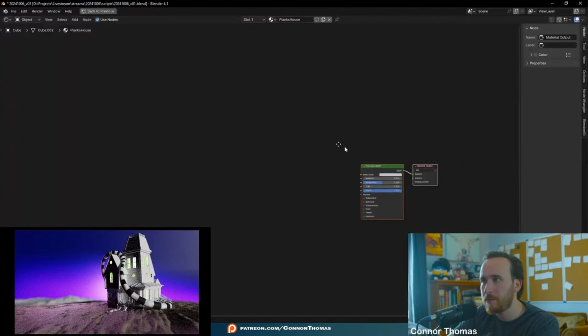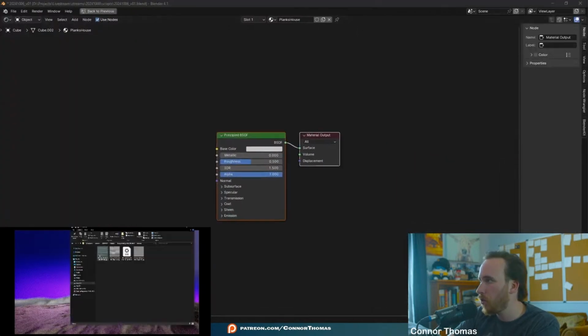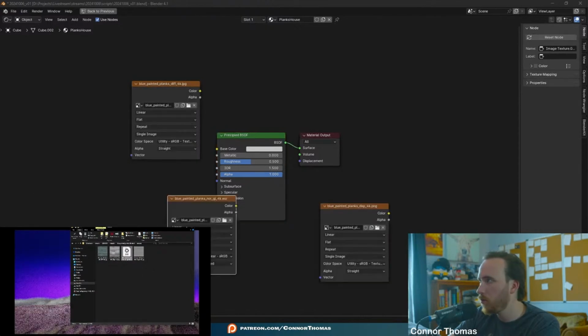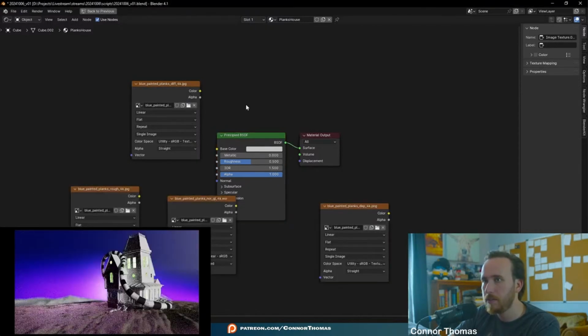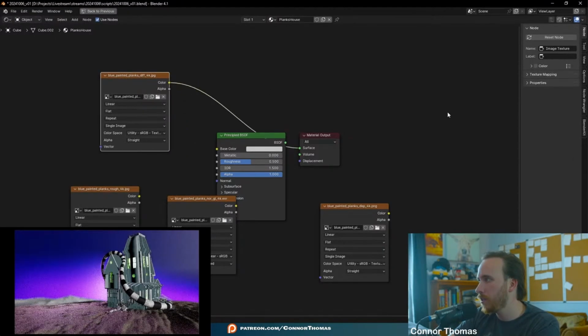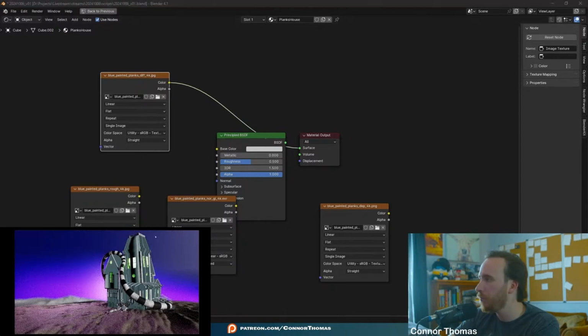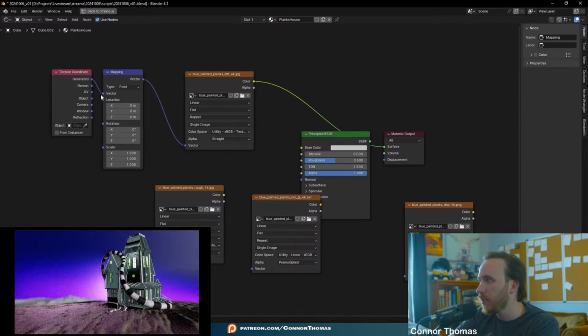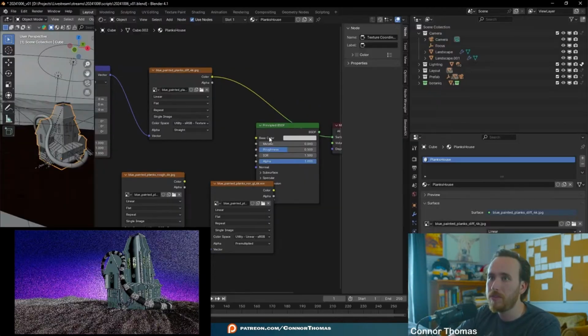Inside of our planks house, we're going to import our textures, which all we have to do for that is just drag over our images, and use the displacement, normals, and our roughness. And all of these are probably sRGB. Let's first take a look at these planks just to see how they're oriented. Yep, they're really screwed up. And actually, that's probably because our UVs are really wrong. If we use generated for the vectors, it'll give us a different result, and normals is going to give us a different result, but we want UV, okay? Because the way we're going to set this up is we're going to UV unwrap our house to have the correct amount of textures in it, and how we want that to be oriented.